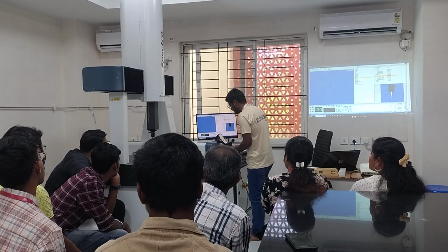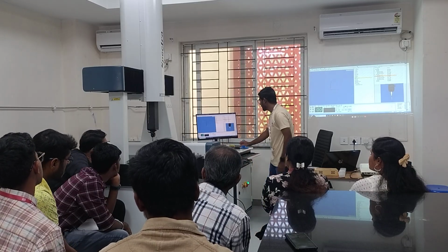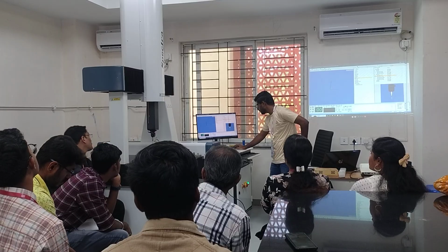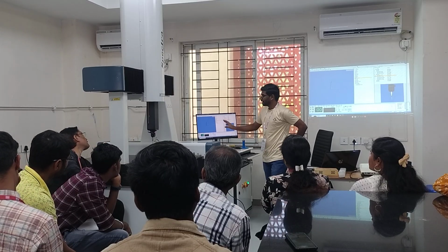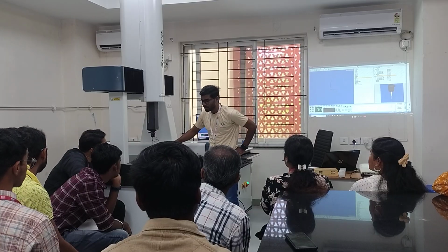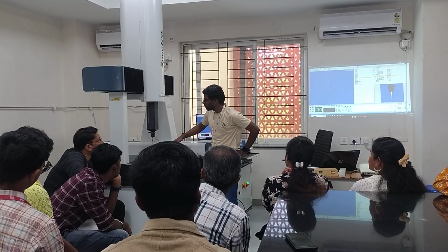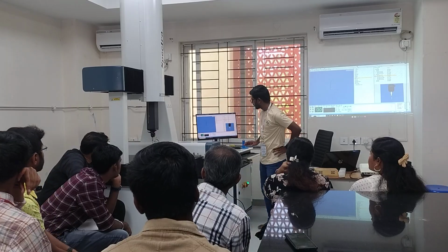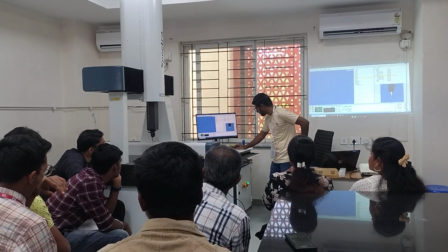Before this, we have to check another setting here, which is the approach distance. This is basically used when you are automating. If I want my sensor to be here, approach distance is how far it should go and search for the body. It cannot go for infinite distance, okay? So I have kept it at 1 because I'm not going to use any autonomous mode here.